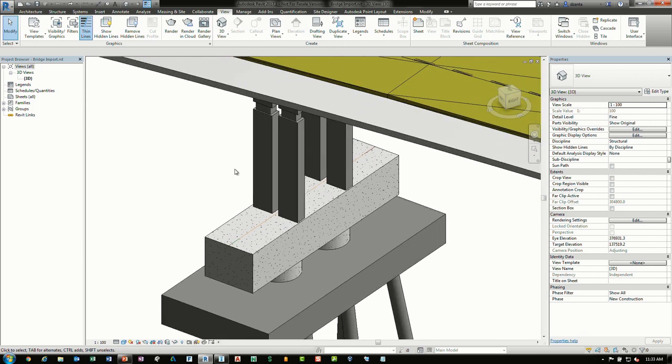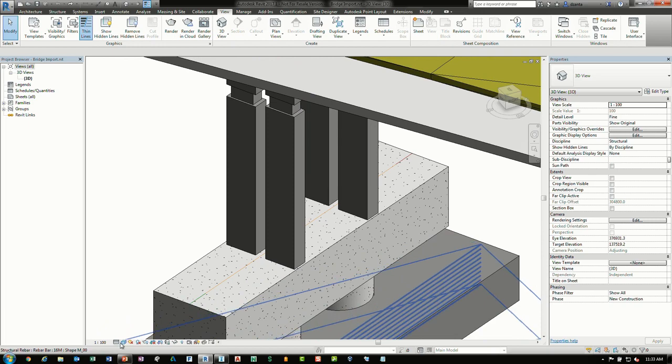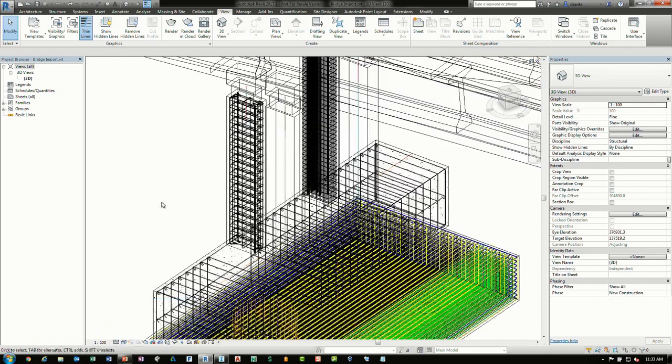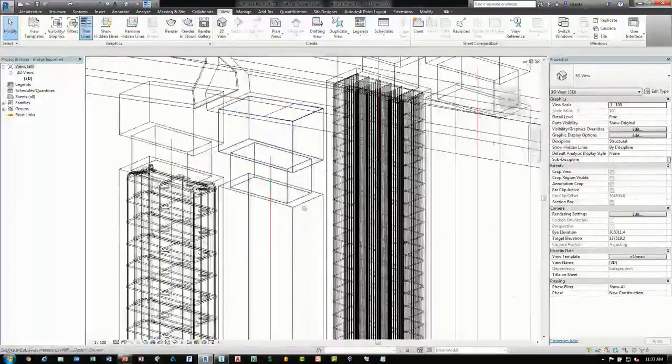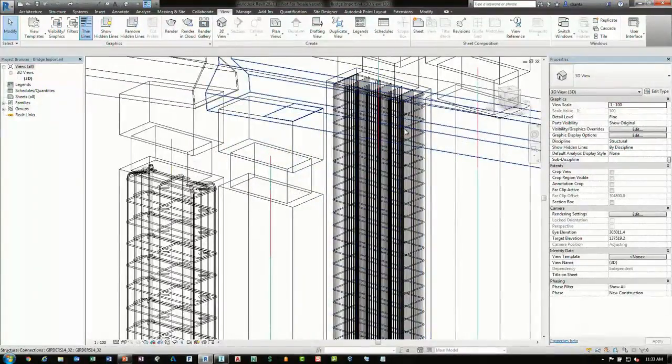The next part is looking at the rebar information. And let's head over to a wireframe view. And you can see there's a couple columns that I put rebar in here. The one on my right, this one here, is using the standard rebar commands within Revit. Again, I'm not a structural engineer, so I just threw in tons of rebar. And that process is very iterative. It just takes time. You put in a rebar, you specify things like the divisions and then the quantity and so on and so forth.